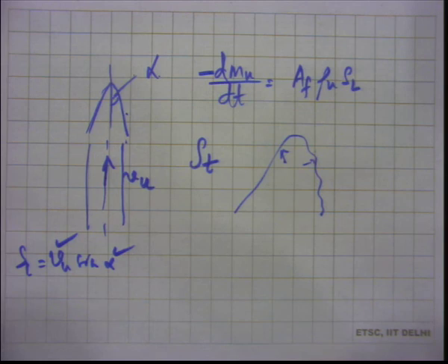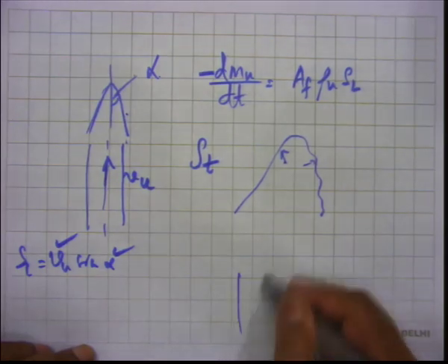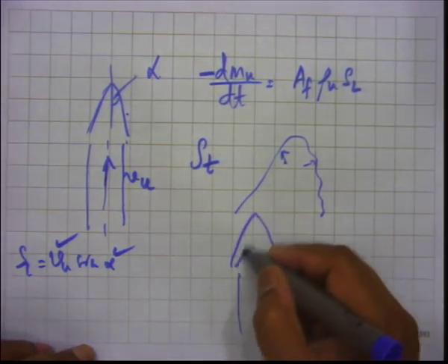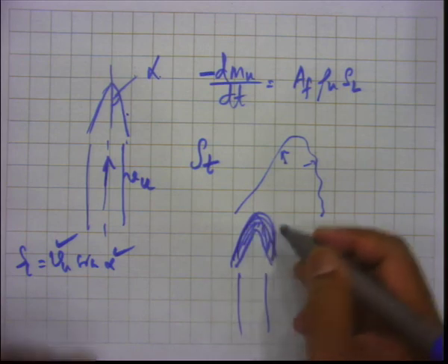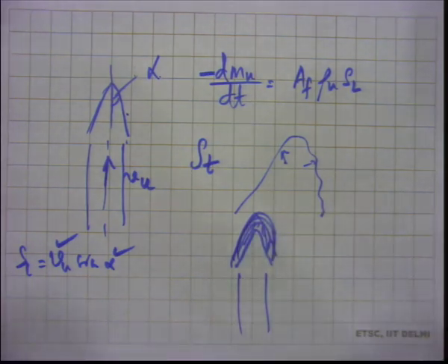For turbulent burning velocity, it will be more difficult, because defining that area, the flame zone itself is difficult. The flame zone is now becoming, in case of turbulent situation, like this, some thick zone. Which area, where to take the velocity, is there a cone, we do not know all that. So, this is all going to be somewhat difficult.